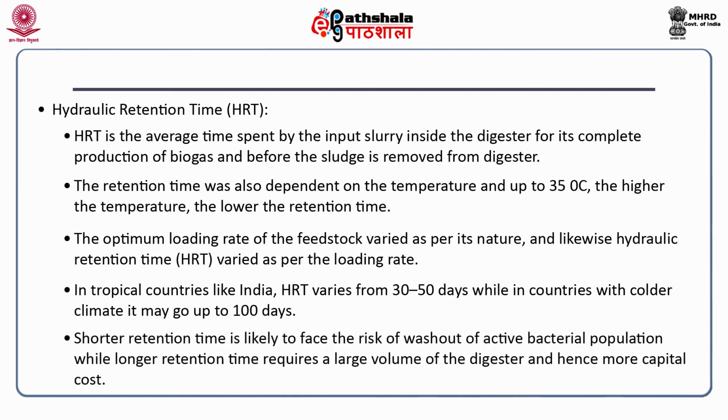A shorter retention time is likely to face the risk of washout of the active bacterial population, while a longer retention time requires a larger volume of digester and hence more capital cost. But this HRT depends upon the substrate which we use for biogas production.